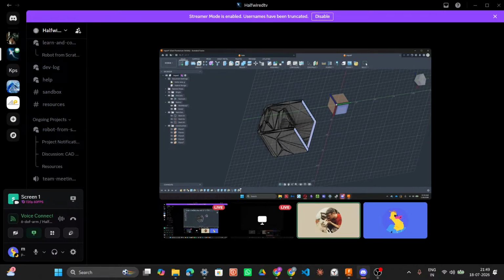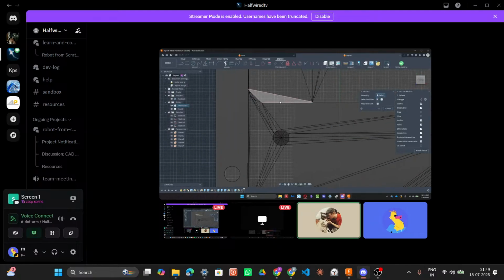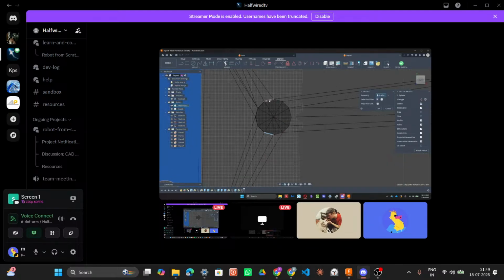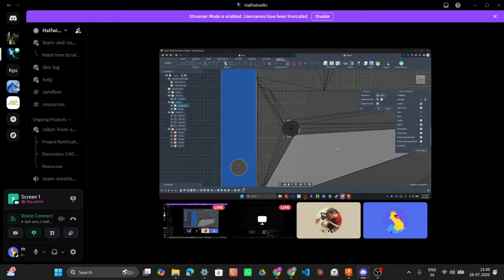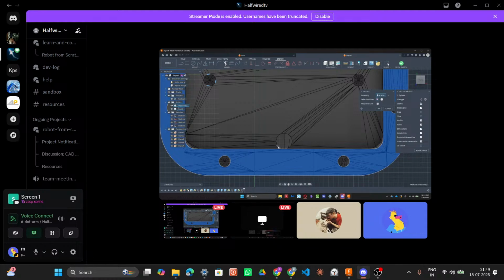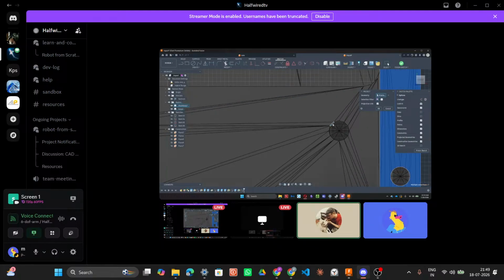So do a sketch on there, project in. I'm going to project in this surface, these holes. In fact, I'm only going to do one of those holes so I can make sure they're symmetric.